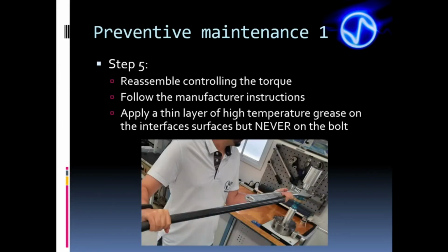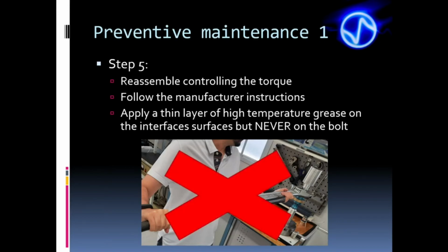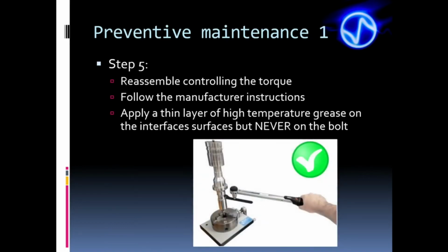This excessive pressure stresses the stack and the stud unnecessarily. Therefore, over-torquing must not be used for interface wear compensation. Applying a low torque is desirable because the more torque we apply on the stud, the more unnecessary stress we put on the stack elements and on the stud itself. This increases the tension concentration on the parts that may cause damage to either the stud or the elements.